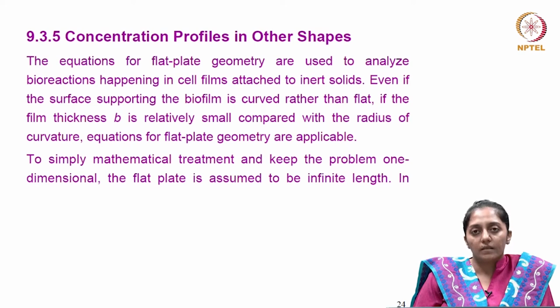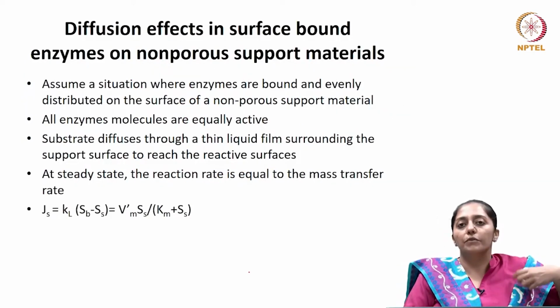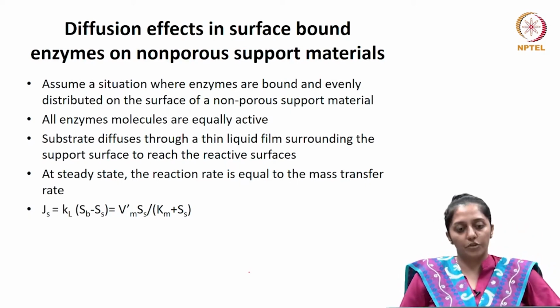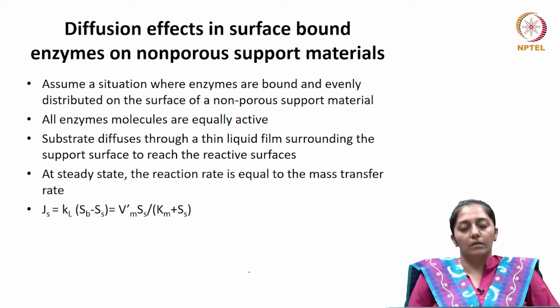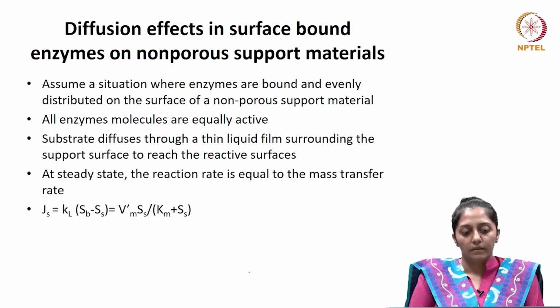To ease the mathematical calculations and to keep the solutions one dimensional, the flat plate is assumed to be of infinite length. So, let us see how to characterize the diffusional limitations in a flat plate geometry or immobilized cells on flat surfaces.